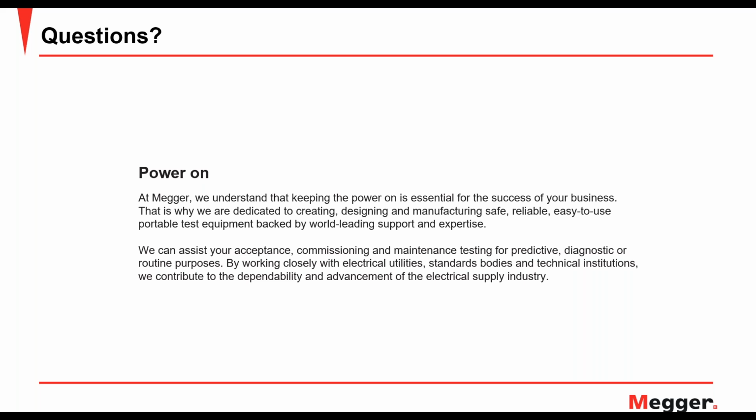Say I zoomed into the short circuit SFRA test and I'm concerned because they're not within that 0.1 dB limit. You could always go over to interwinding. It's considered an optional test, but if you did a capacitive interwinding measurement, you could check at the 60 hertz, or 50 hertz, and see how those three phases are behaving. It would mimic basically doing a CHL test on a three-phase transformer. However, you're now doing a CHL test on A phase, B phase, and C phase, which is kind of nice.